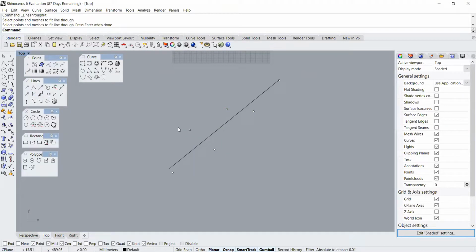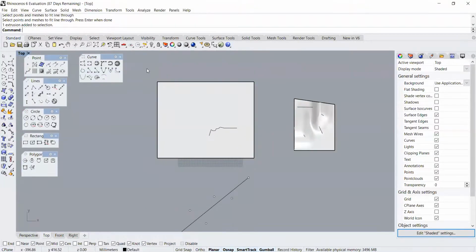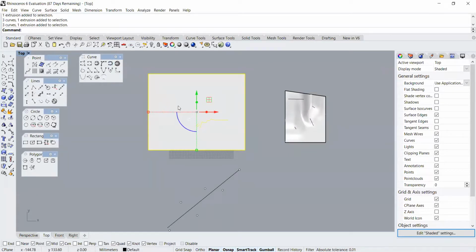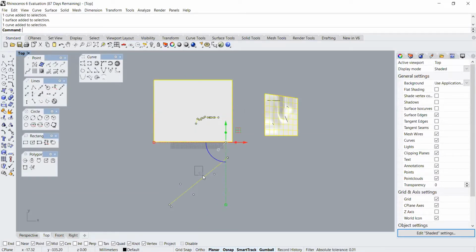And also for selection, whenever we are selecting an object, we can click on it, or we can drag it behind or drag it front. In AutoCAD, dragging behind and dragging front is different, but in Rhino, it's the same. And in order to deselect it, press Control and then click. In order to select multiple, press Shift and then click all the objects, like this. And then to deselect or remove from that selection, press Control and drag. So drag your cursor around it, then it will deselect.